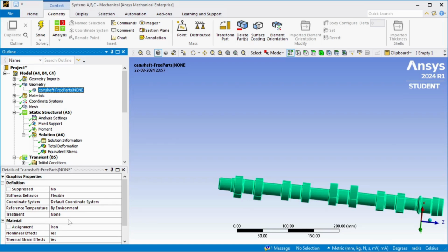Cast iron, particularly chilled cast iron, can be produced with a very hard surface layer. This hardness provides excellent resistance to wear, which is essential for a component that experiences constant contact and friction.